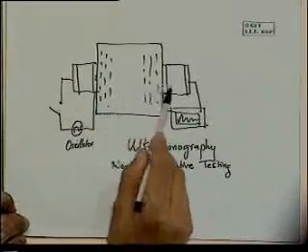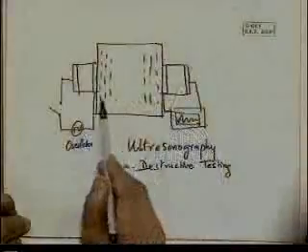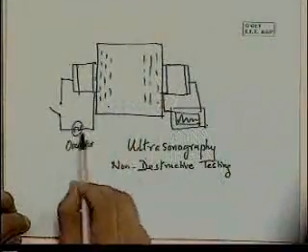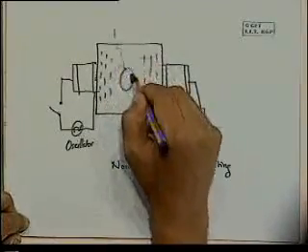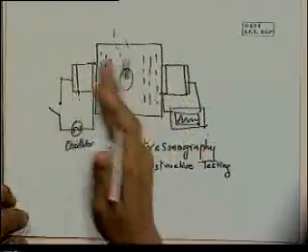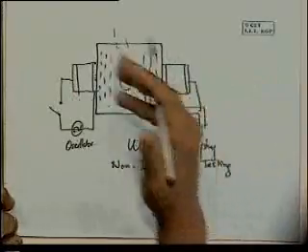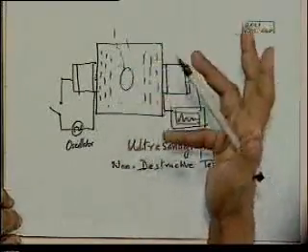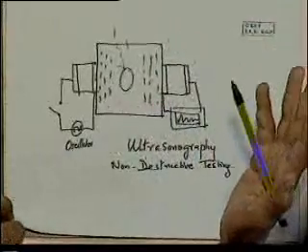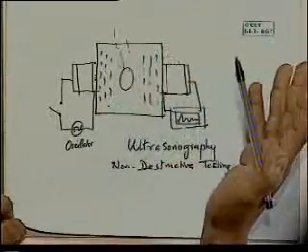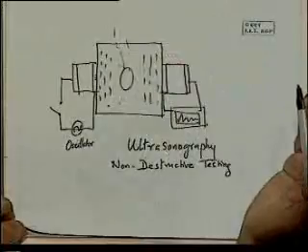And so I could do something like this, put two of these transducers and pass these waves through it. When it encounters, let's say, some kind of a defect, it will scatter differently than simply passing through this material. So when it comes to a pore, a void, a crack, it will behave differently than if it's a perfect material. And so by doing this kind of testing, I can evaluate my material without ever having to break it up or damage it in any way.